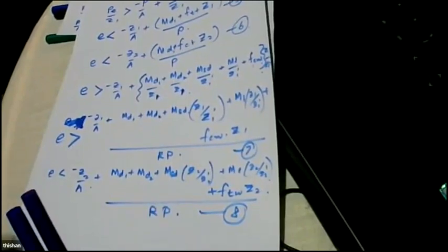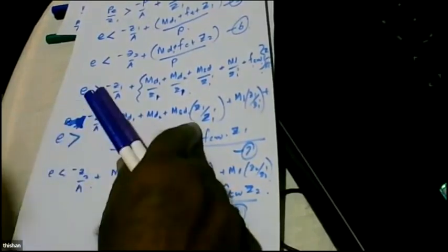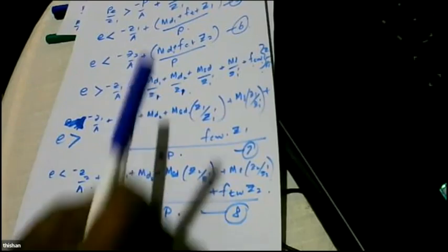MD1 is applied at the transfer, MD2 is applied when we place the beam and pour concrete. Then the superimposed dead load moment and the live load moment come from the analysis. But for those, the Z values are different because now you have a bigger section resisting the moments. Plus whatever these FCW and FTW values are. And you can see the difference between transfer and working. Working gets the R factor, transfer does not. So we have four equations. Four equations means we can draw a Magnel diagram, right?